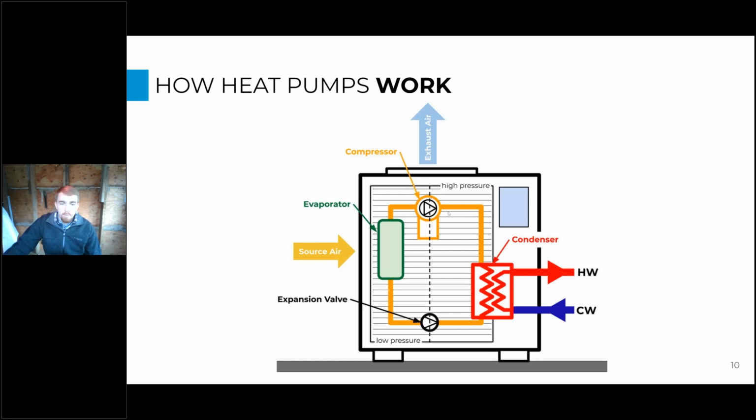And really the only thing we're paying for here is the work done by this compressor to actually change that pressure. We're not adding heat, but we're doing work on the refrigerant. So we do have to pay for that in power, but since we're harvesting that heat from the air, now it only requires about a third of the power to put that heat into the water. So if you put 1 kilowatt of power in, you're getting about 3 kilowatts of heating out. And that changes with different variables like air temperature and the refrigerants you're using. But in general, that's a good rule of thumb.